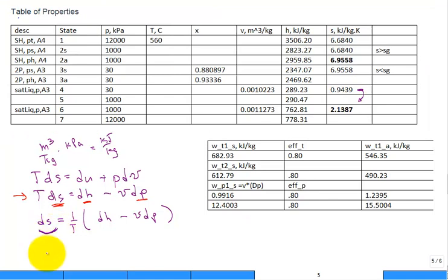Okay, so what we want to do is add a small amount to account for going through that pump. And you say, well, we already calculated what the change in enthalpy was going through the pump. Wasn't it our VdP divided by our isentropic efficiency of that pump? Sure. And then we have minus VdP in this equation. Then you divide by the absolute temperature. You have to put that in Kelvin. You can't leave it in degrees C. And so this is an equation to estimate the change in S.